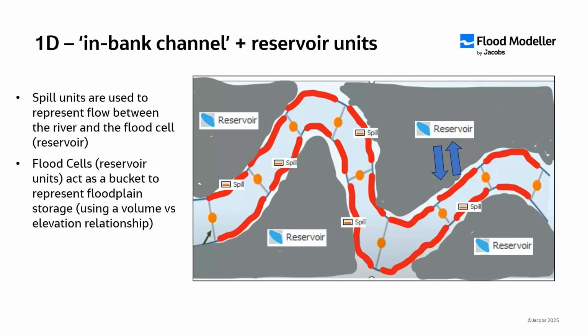The reservoir units can be generated in Flood Modeler using the tools, and what they represent is a volume versus elevation relationship, and that can all be defined within Flood Modeler. And what this type of modeling allows us to do is to produce flood mapping for 1D only models. So that would be really useful for like the Environment Agency flood maps, for example.